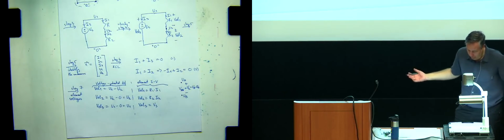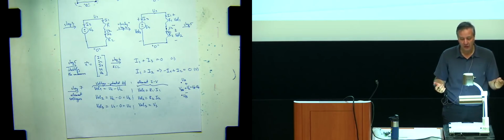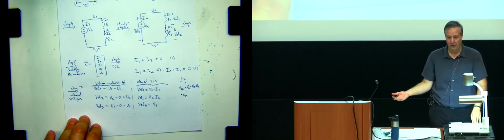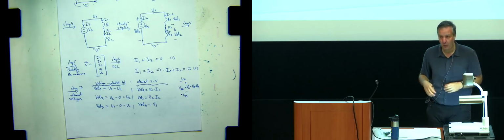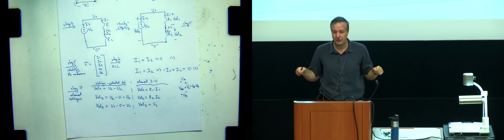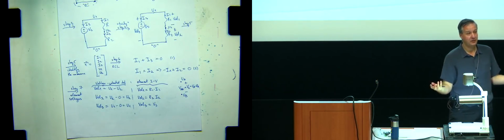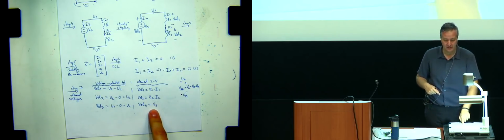Now from these two sets of equations, we can eliminate V element as an intermediate variable, and we can link the potentials to currents, which is what we want. We want to form the matrix that has linear equations, linear combinations of currents and potentials, not voltages. That's why we need both of these.